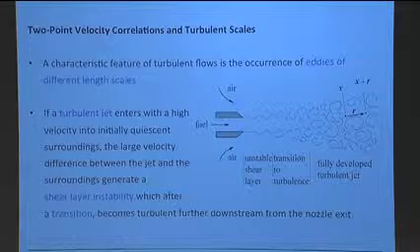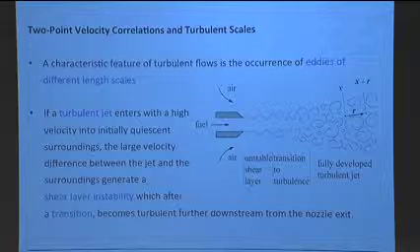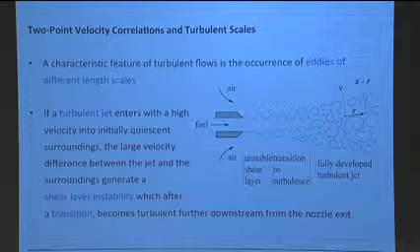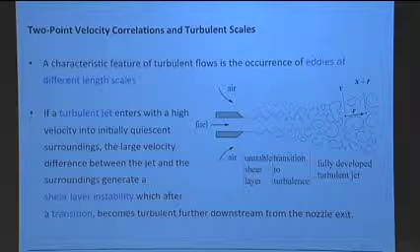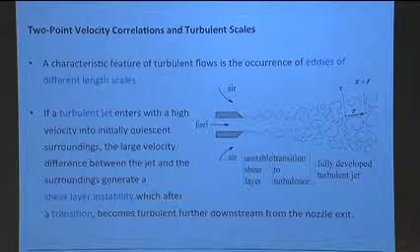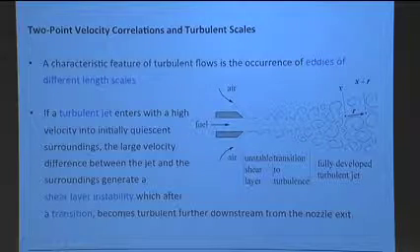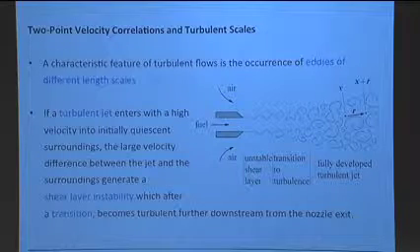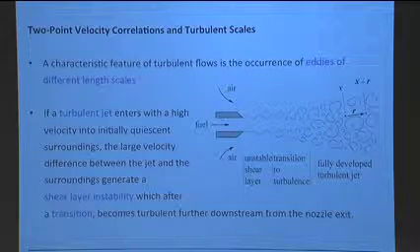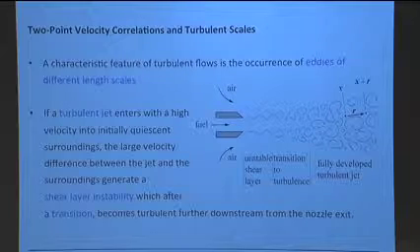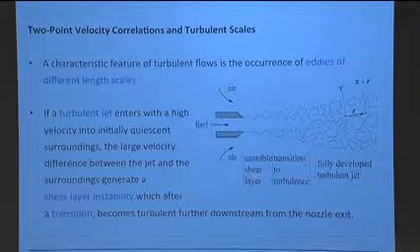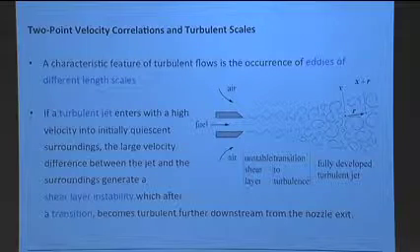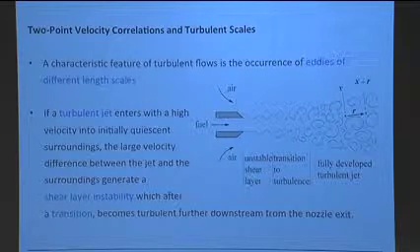The shear layer might become unstable if the momentum is high enough that viscosity doesn't dampen instabilities. That shear layer might become unstable, and it breaks up, and it might form these vortices. Now, when we want to conceptualize turbulence, then we often think in terms of eddies. Okay, and the notion of an eddy is not exactly right, but it helps a lot in trying to think about turbulence.